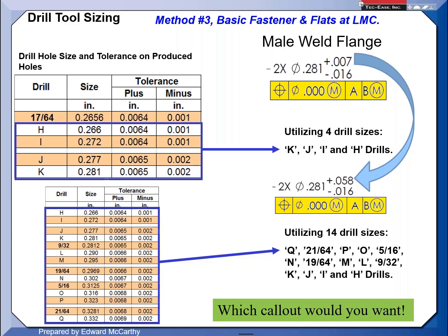So it's really about this: all these challenges were about really asking the right questions, not compromising design intent. There are tools in the GD&T toolbox, in other words, in the dimensioning and tolerancing standards, where we have assigned formulas. You can calculate what we call boundaries.